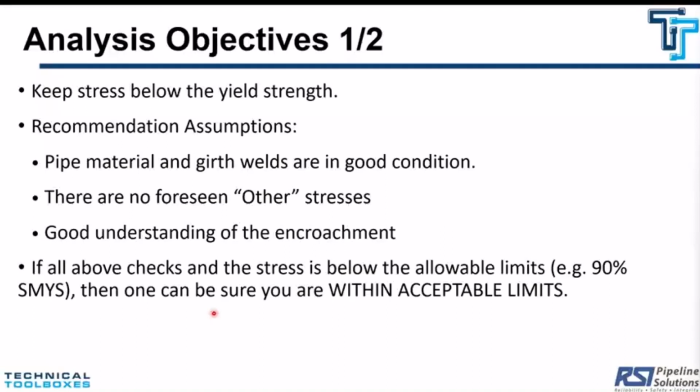Because there could be certain conditions that the tool doesn't know, so it doesn't include them in the calculations. I'm just going to give you some quick examples. I gave you one example already: in case you have features such as dent and metal loss, that requires a separate treatment. But if you have features such as fittings, T connections, valves, or even segments and sidebends, if they are more than about a few degrees, those are the things that may require a higher level analysis.